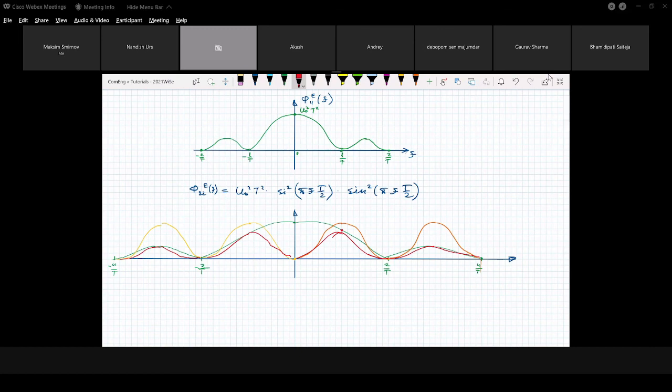And we can actually compare these two plots and see what happens. For the rectangular pulse, this is how it looks, and for the other, I hope you can see this resulting red line. This red line corresponds to the final result that we have. We can say that it's our phi superscript e of f. So we have wider spectral density, but we don't have components at 0.